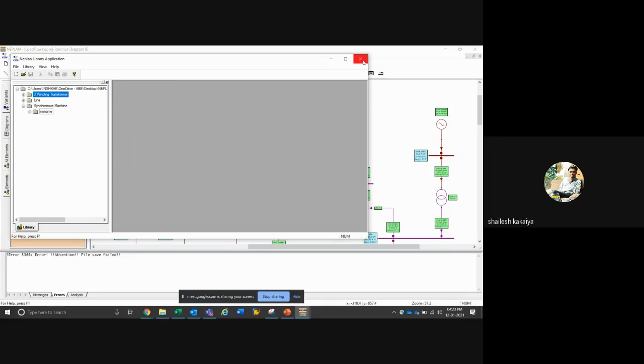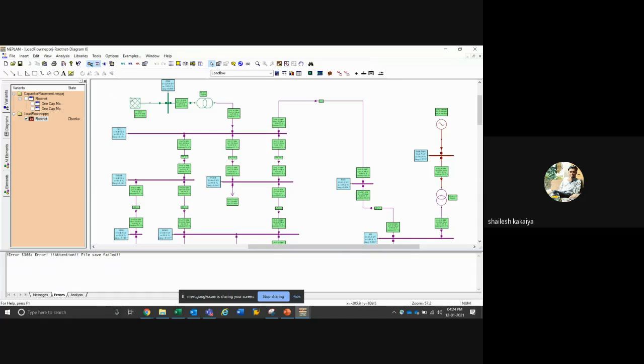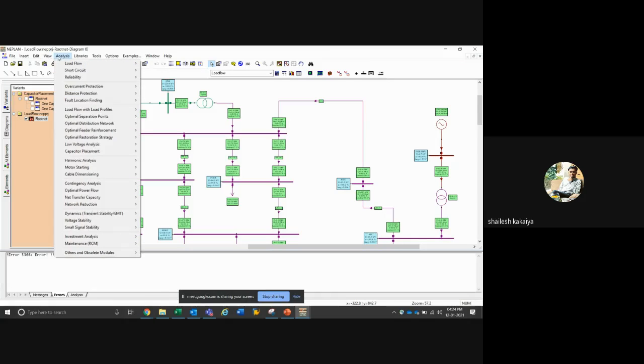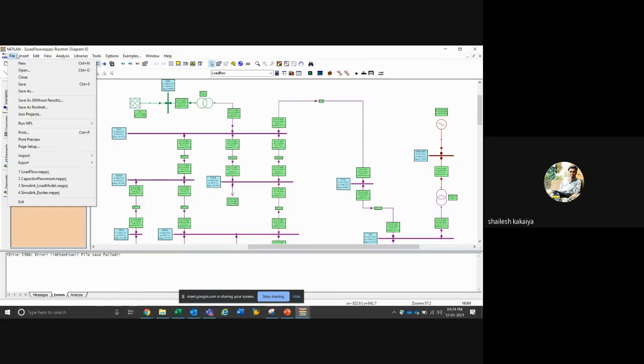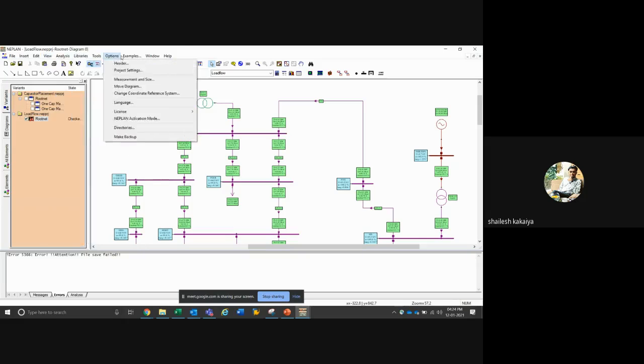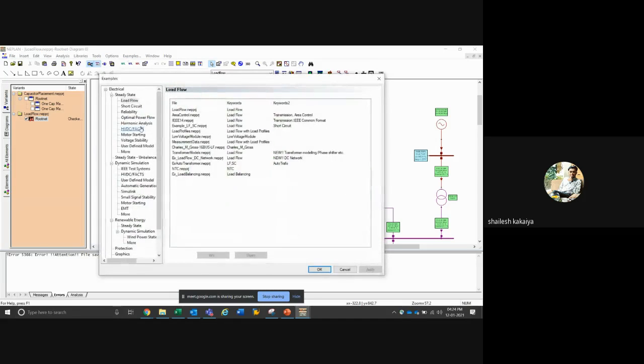Another advantage mainly is that overcurrent device modeling is very simple. In other softwares which you are already using, you might have seen that protection modeling is quite a difficult job. You have to model it as a block diagram, just like a control circuit diagram, and then model all the relevant logics. Only then can we simulate protection coordination.